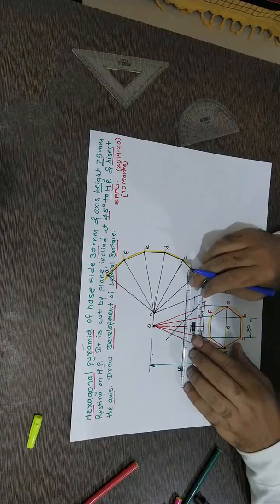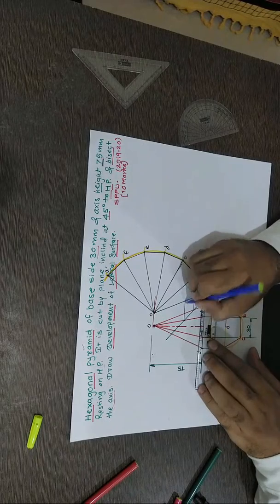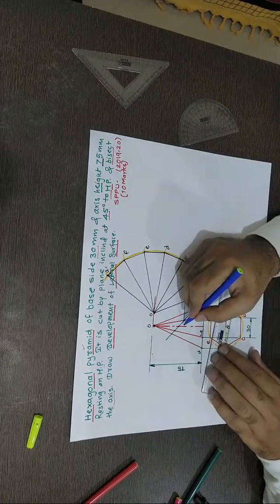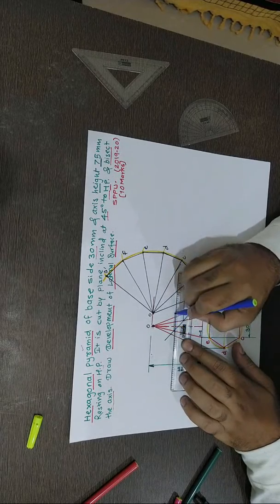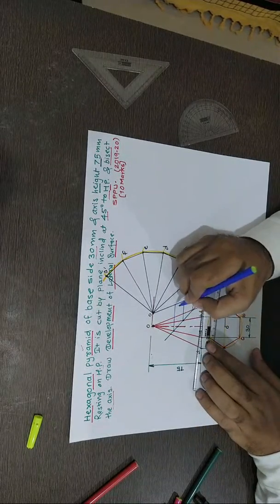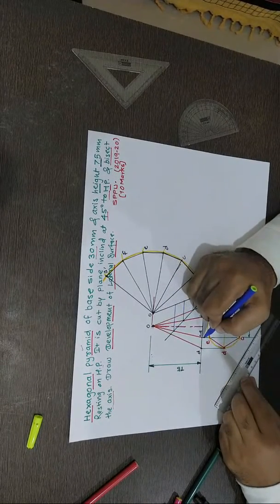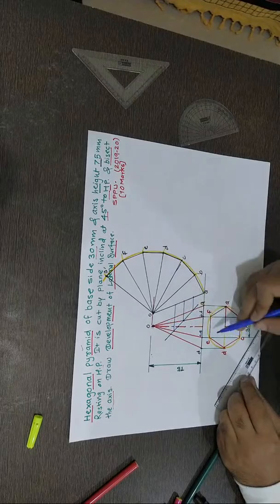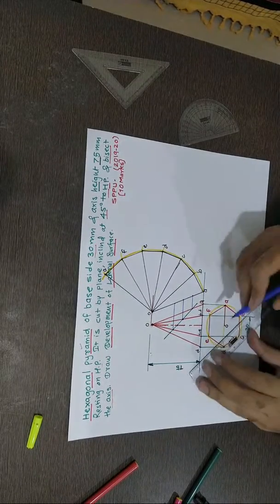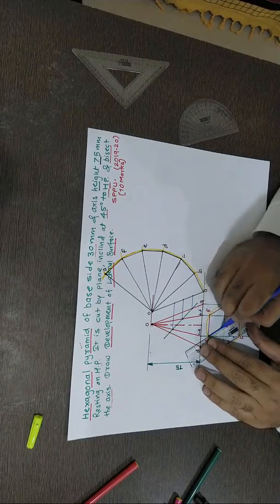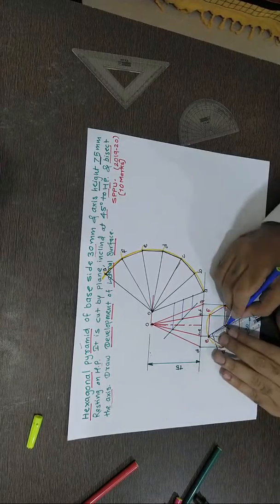Now project this point of intersection onto this true length here. We are not interested right now in the axis, so I'll skip the axis. This is another. So what's the concept? This edge indicates CO and EO. So these two slant edges, CO and EO, I'll join, to avoid confusion about how it will look in the top view.